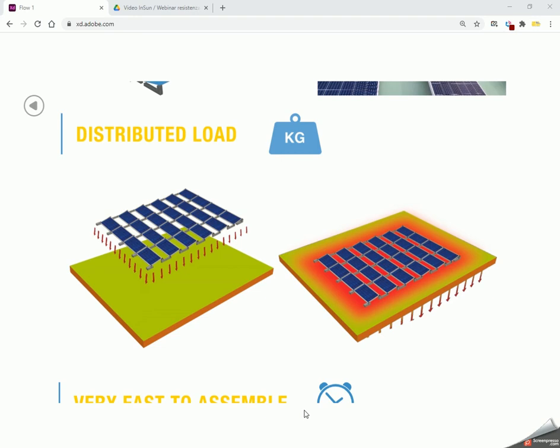Yes, Ilona. In fact, the Connect system has two fundamental aspects that define it: the strong wind resistance and the low load on the roof. It is a conformation that guarantees loads on the roof that are evenly distributed, as you can see from the scene. These loads never exceed 20 to 25 kg per square meter. The Connect system allows the weight to be distributed evenly both for small buildings and big buildings. Therefore, the distribution of weight is guaranteed and even because of the linked rows. This feature is valid for all our systems in general, specifically for the Connect system and for all the inclinations of this system.